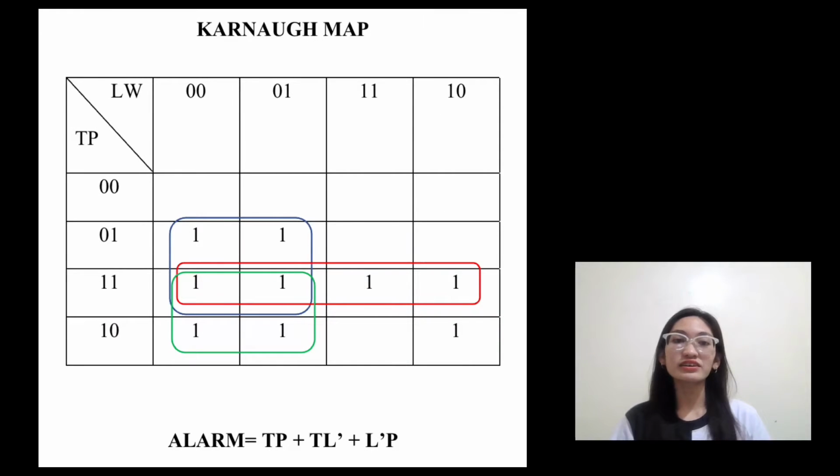You can see here that we use another technique, which is the K-map, to simplify Boolean expressions. It can be observed that we have arrived at the same expression as the one we obtained using the truth table and Boolean laws. Having obtained the simplified logical expression, we can now decide on the type and the number of gates required to realize the expected logic for every output bit, which further results in the complete design of the desired system.